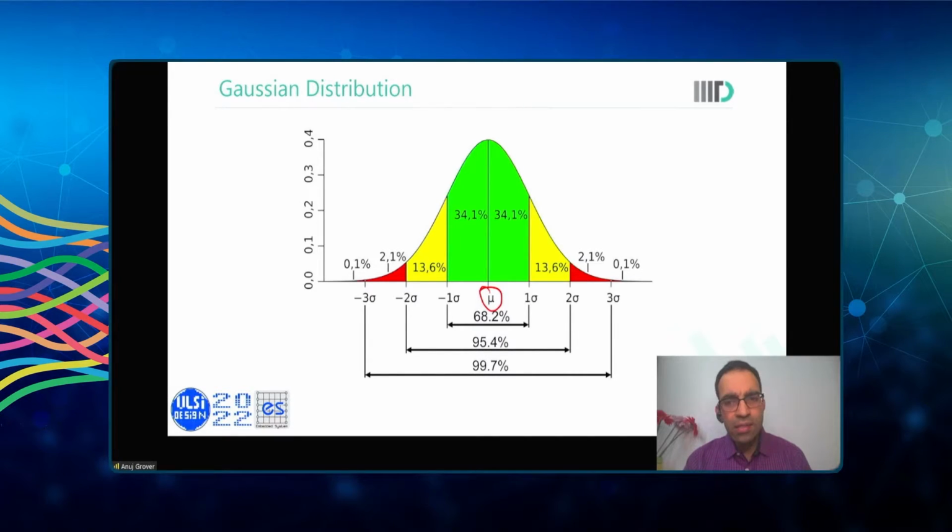So how many memory cells are we talking about? For the sake of simplicity, let us say 10 raised to power 6. So there are 10 raised to power 6 memory cells, and if I qualify stability criteria for plus minus 3 sigma of the cells, the failure rate is 0.3%. Am I right? So 0.3% of cells would fail. Sounds to be very less. But what that means in terms of a 1 megabit SRAM capacity is that on every die, you will have 3,000 failures.